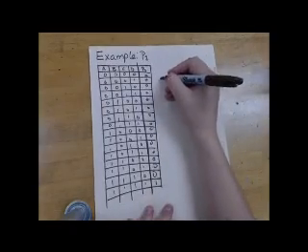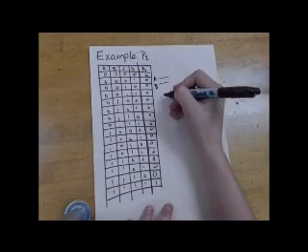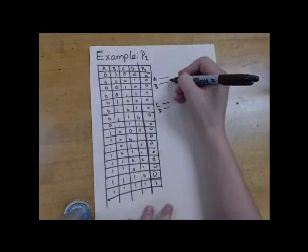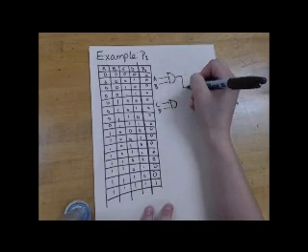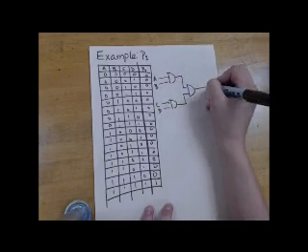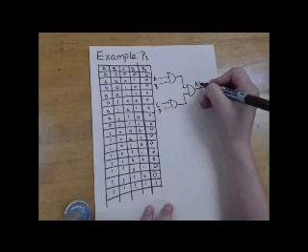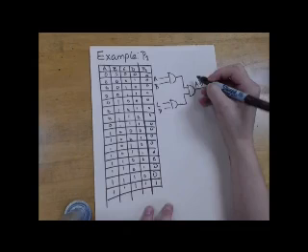So we know that we're going to have to be able to filter these somehow. So given A and B and C and D, the logical thing to do, no pun intended, is to have two AND gates to filter out this, and then have both of these AND gates filter into another AND gate, thus giving us A dot B dot C dot D.